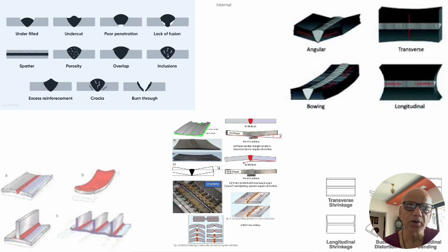So you should not try to bridge the burn through gap in one go. Rather, use a buttering technique after, of course, grinding and re-preparing your edges for a smooth transition. Slowly bring up the material by depositing on both edges to a desirable root gap, and then use proper current to fuse it again and join them together.